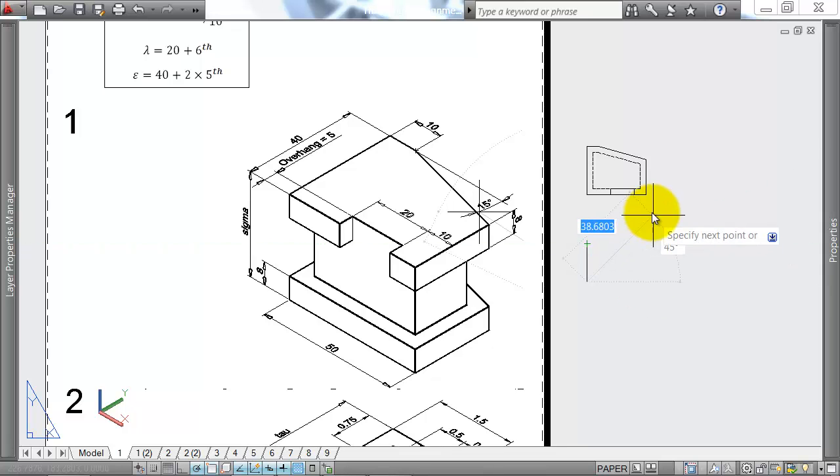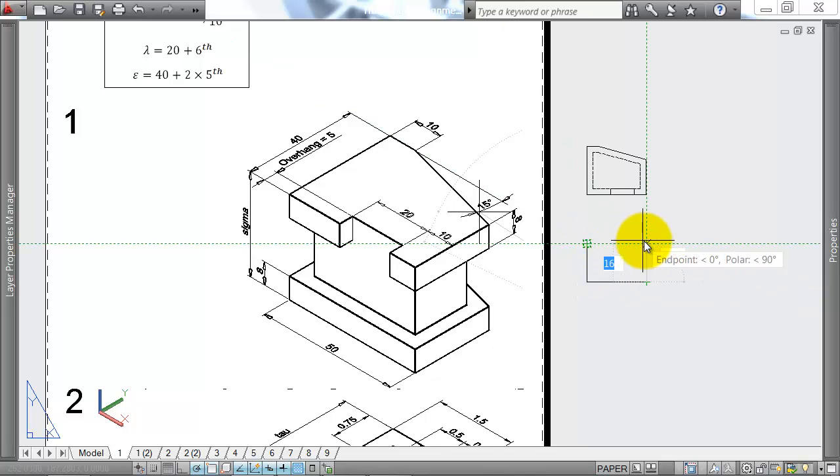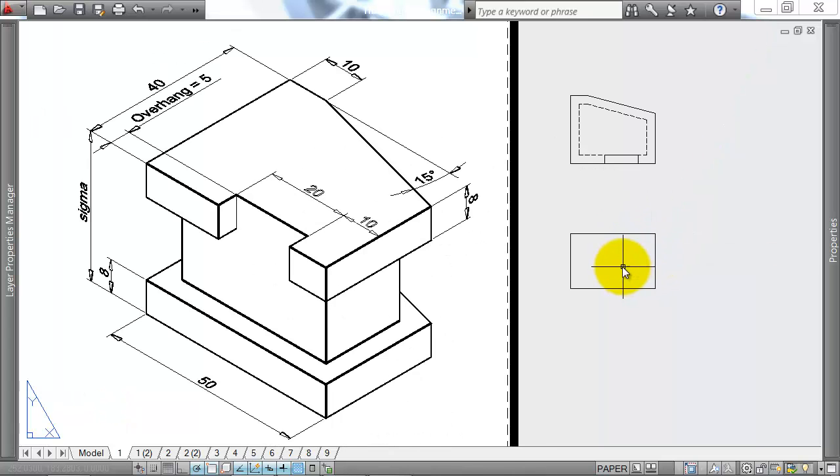The width of this view is always equal to the width of the line above. So if I was drawing this on paper and I had construction lines, I'd drag my construction lines down from that corner. In AutoCAD I can do it with the mouse. And I can use this construction line to get back there, close that off. Now each of these top and bottom pieces of bread in this sandwich, for lack of a better term, they're both 8 units high. So I can offset these lines 4 units, find the center of the shape.